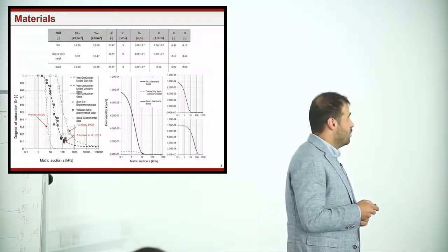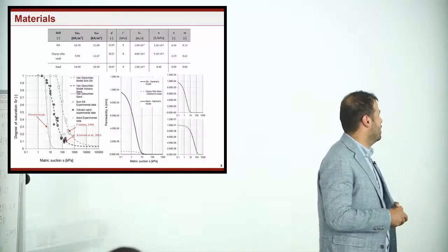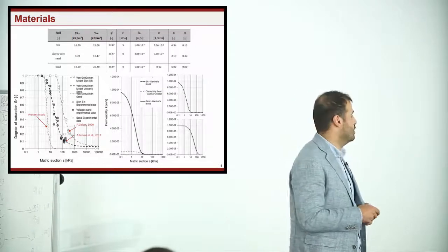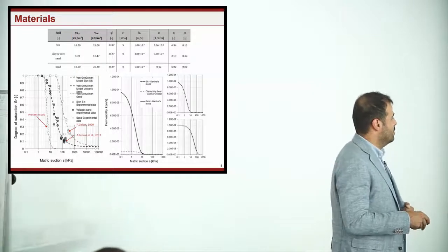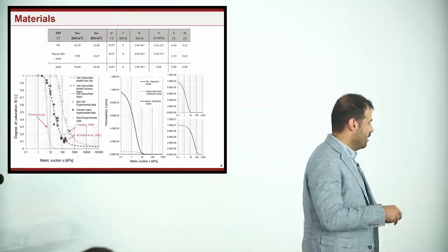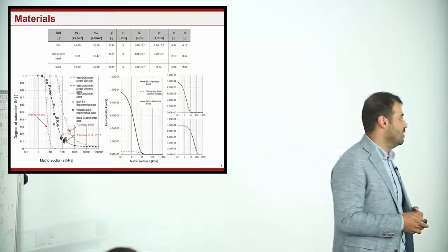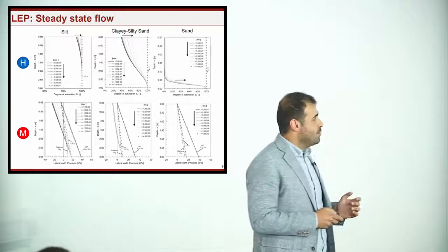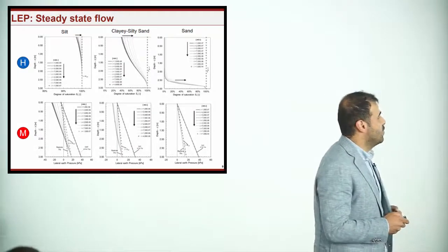Moreover, the water retention behavior plays an important role on the shear strength and its evolution with time, and we need to characterize it well in order to have the resolution of the Richards equation, to see how the matric suction is changing during the rainfall event. The same approach can also be presented in the limit equilibrium method.